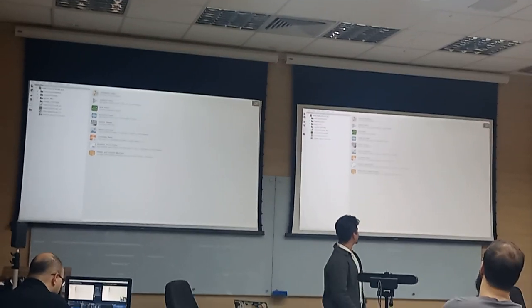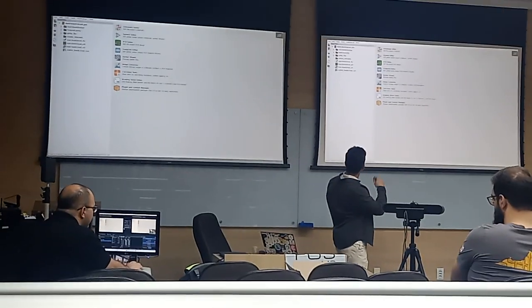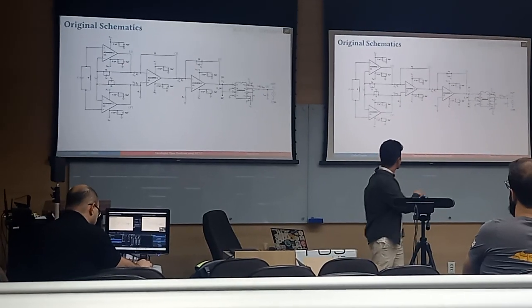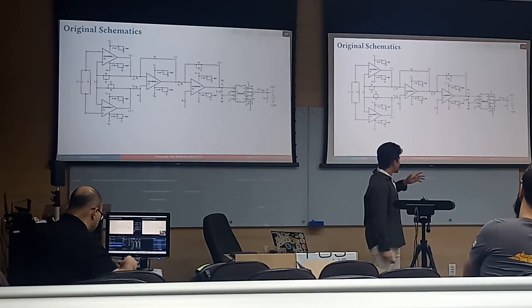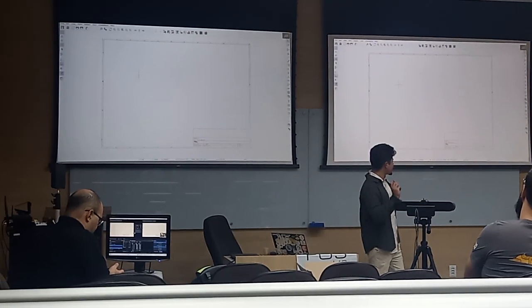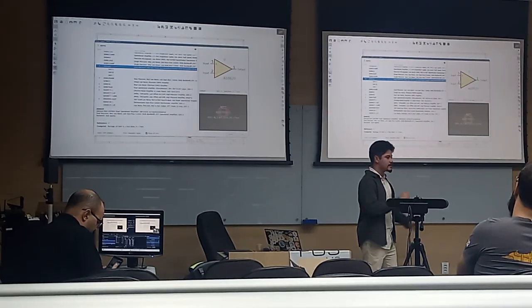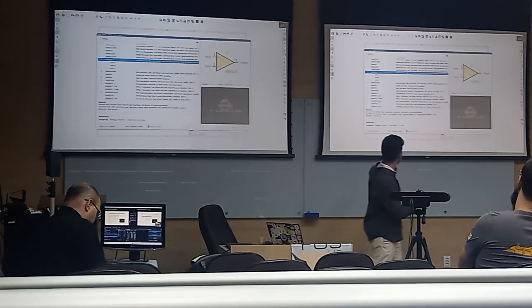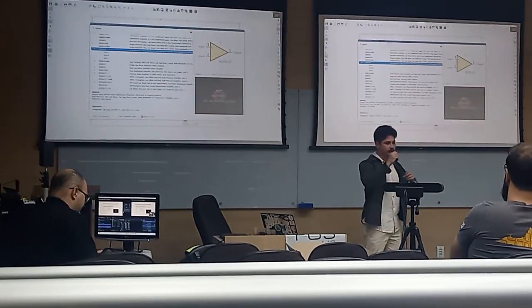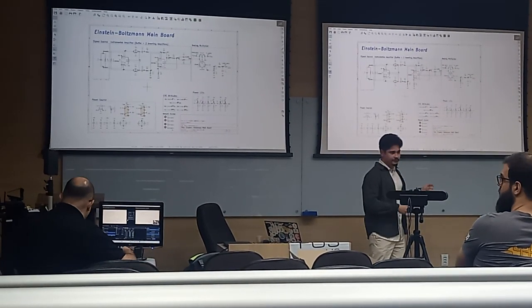Designing with KiCad, we get this intro screen, and we have a lot of features to access here. The first thing that I want to do when making a board is the schematic part. So this was the original idea, but how can we do this in KiCad? The idea is to open a blank canvas and start placing the components in the correct way. You choose the component, choose the specification, see for example the fabrication that you want. You can import some external symbols from the manufacturers and make your board. And this was my schematic. A lot of work to do.